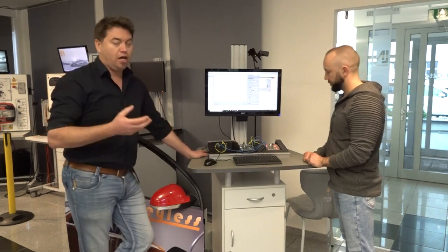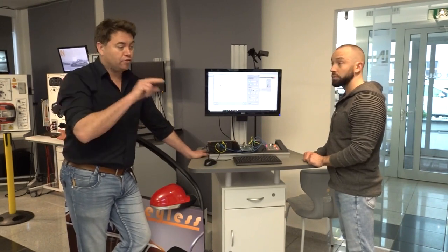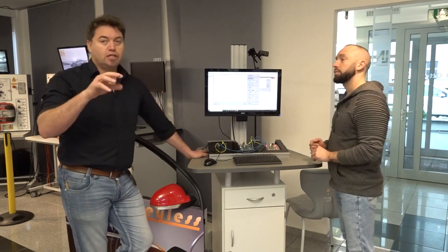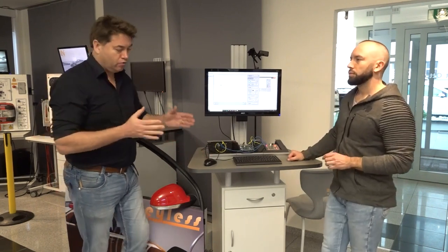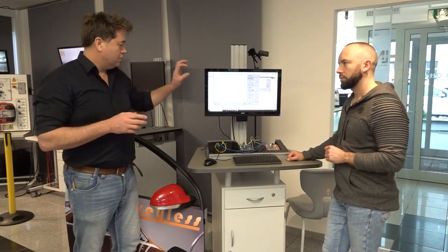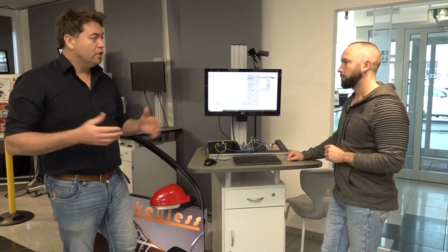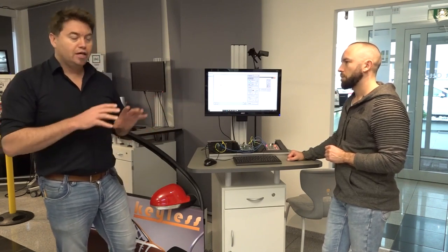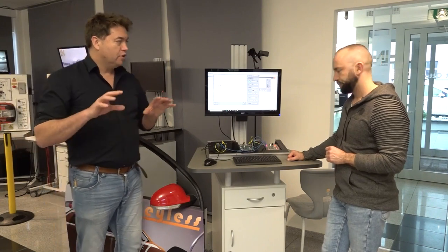Understand where these CAN nodes are around the vehicle. You might have to start going to various nodes, the gateway, to see where the message is. So you've got various points where you have a nice signal, and then you have other sections where the signal is ruined. There's a short circuit, an open circuit, a high resistance, and that's the basis for doing the diagnostics on these systems.